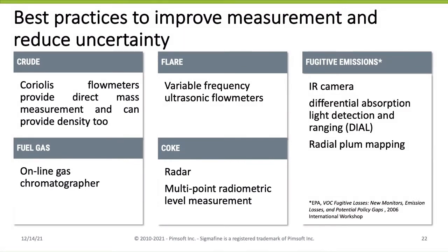For flares, to improve the measurement in flares, which typically have very different flow rates. So typically they have a small flow, but when there is some upset in the plant, the flow rate increases sensitively. So orifice plates, for example, do not work very well in these cases. Ultrasonic flow meters are suggested.